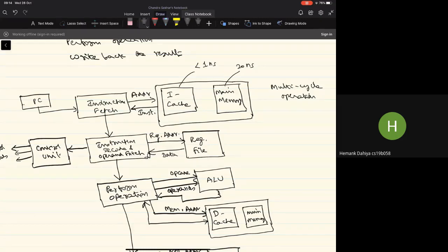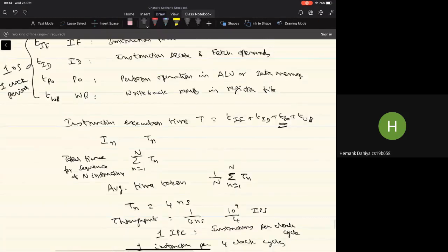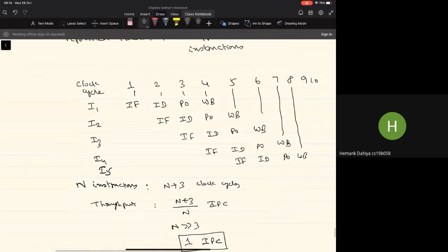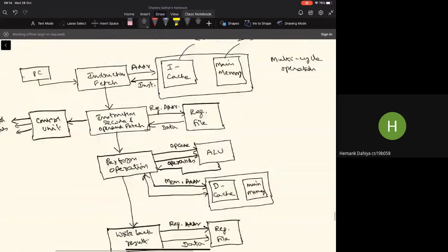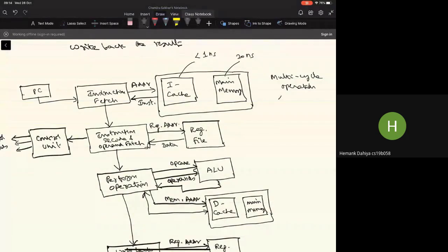So for that instruction, the number of clock cycles taken to complete the execution will be larger than 1, and that will add to the total number of clock cycles required for the execution of the complete sequence of instructions. So your numerator term, which is n plus 3, will not be valid anymore. It will be much more than that. Let's say on the average there are an additional delta cycles that may be required to complete the instruction fetch. So the time taken for the instruction fetch alone will be, on the average, 1 plus delta IF.